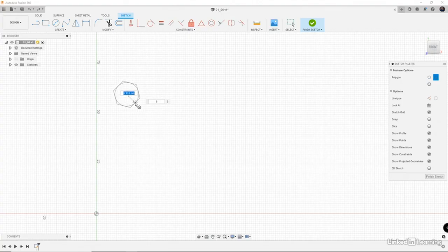And here you can specify a polygon that's driven by 2 points. One, the distance from the center of the polygon to the center of the segment of the polygon, and the amount of sides. So for instance, if we wanted to make a 10 millimeter bolt head, we could do that here by simply going 5 millimeters, and that would give us a distance of 10 millimeters across the polygon. We could also simply change the amount of sides that we have to 4, and we can make a square, or we could come back and do 3 to make a triangle, or we can come back and do 10. So, I mean, there's all kinds of options here that we can do.